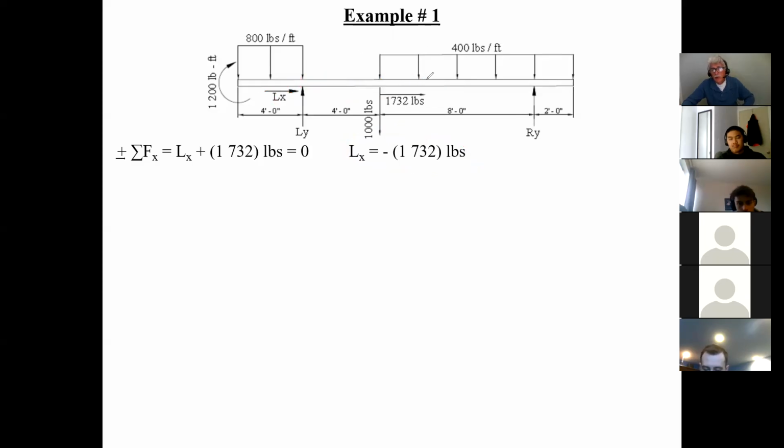So that's where the axial forces go. Here, the axial force, the tension, is 0. The tension here is 0, and the only place I have some tension force is in this little section here. Isn't that amazing? Because why? Because here I don't restrict it. Here, there's nothing to restrict it, and therefore the only place I have tension is right there.